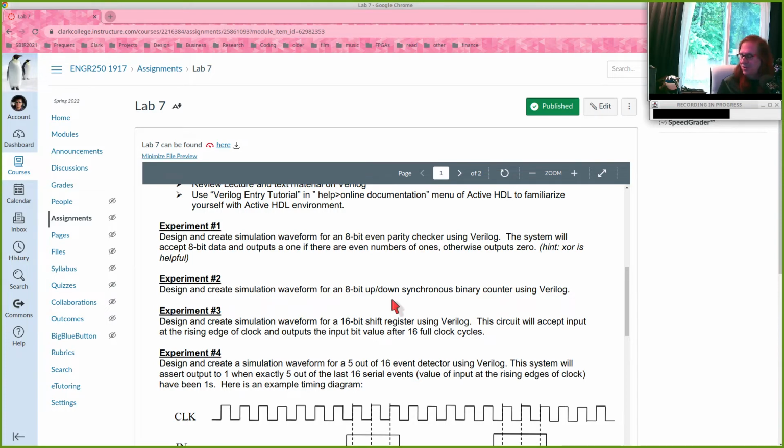And we can do this with flip-flops. We could do this with a state machine system, and we'd have 256 states. Right? Because with 8 bits, we've got 8 flip-flops. But in Verilog, this is going to be a few lines of code.